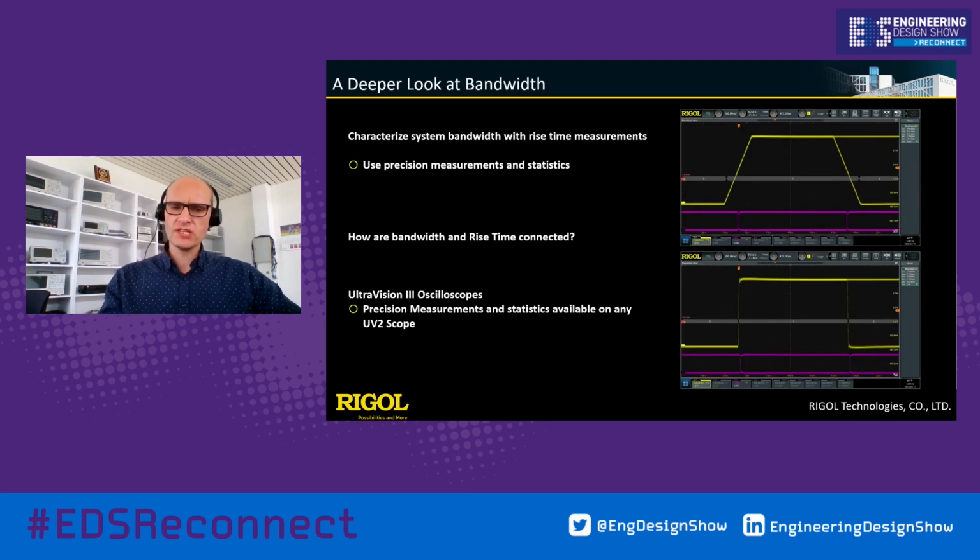The next part, which needs to be discussed, is a deeper look at the bandwidth. The bandwidth is, of course, quite important because the more bandwidth we use, the better the signal is. The rise time is sharper, but we have other negative effects. For example, of course, we need more bandwidth, which is clear, but we can also have some kind of overshoot effects, which can sometimes be a problem.